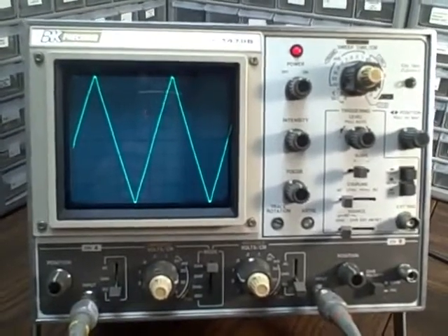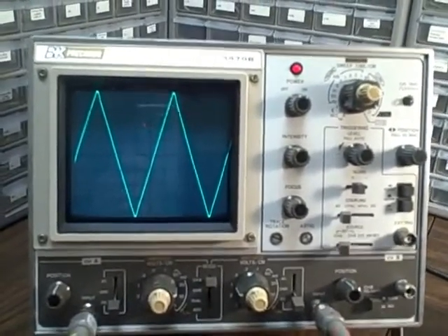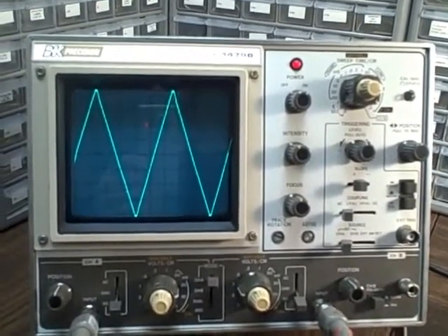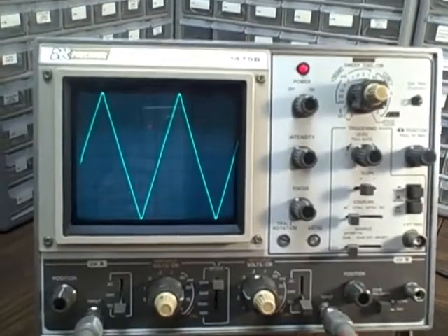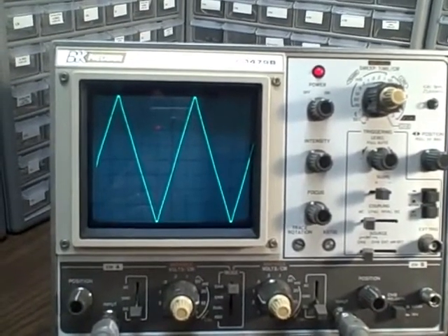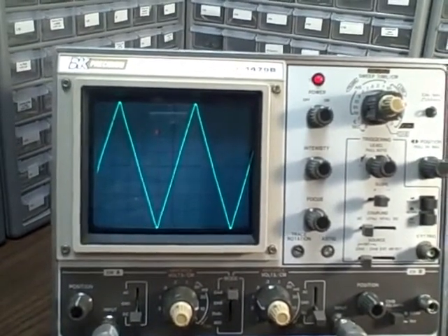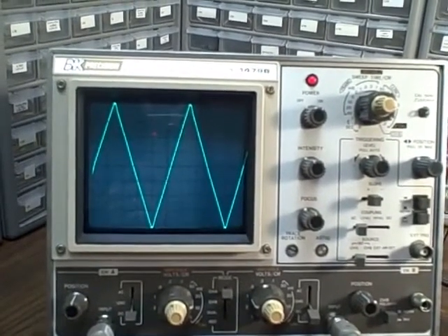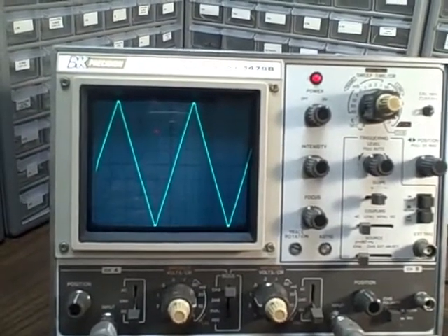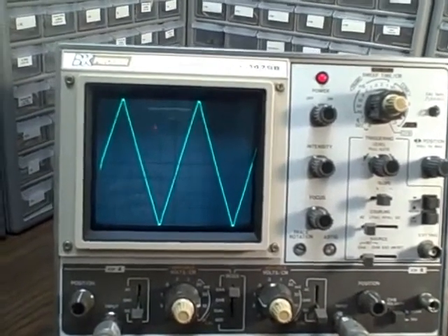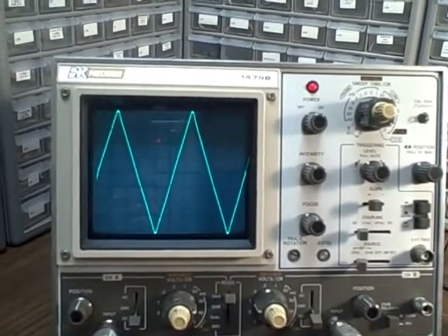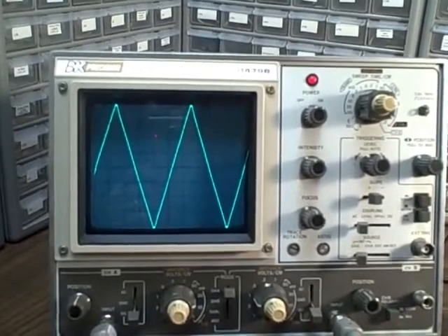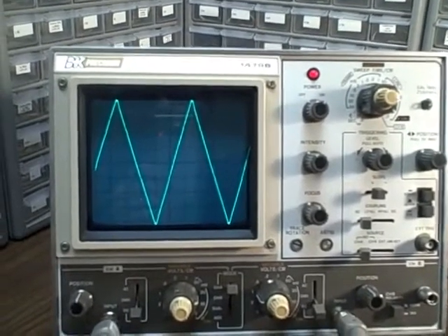So at this point, let's just discuss what happened here. First, we measured our calibration test point. We saw that we had 0.5 volts peak to peak, and that it corresponded to the scale on the screen. And we used that then to test vertical from 1 volt per division all the way down to 10 millivolts per division, and we tracked it very well. We did that for both channels. Both channels tracked and measured voltage as well.